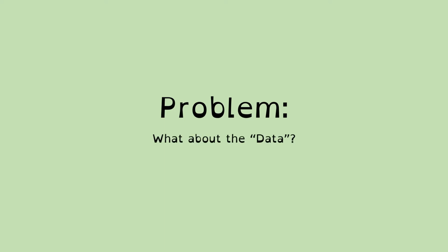We've come to the point in our discussion where we need to deal with a particular problem that I hinted at in the last video, which is that some of the instructions that we've got have data attached to them. These are operations like you want to put a specific value into the A register, or you want to move the contents of the A register into a specific memory location. And so as well as the opcode for this, you need the data.